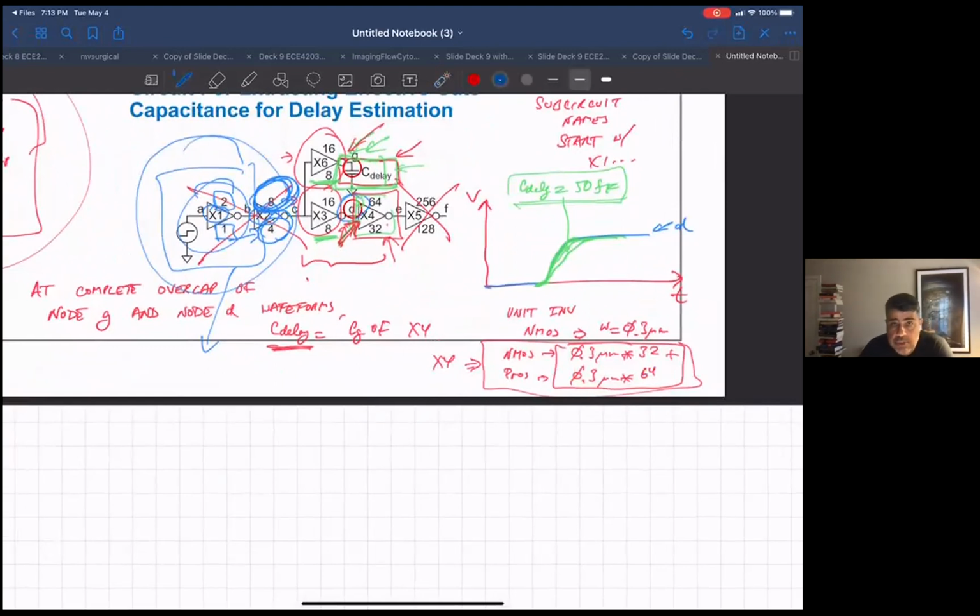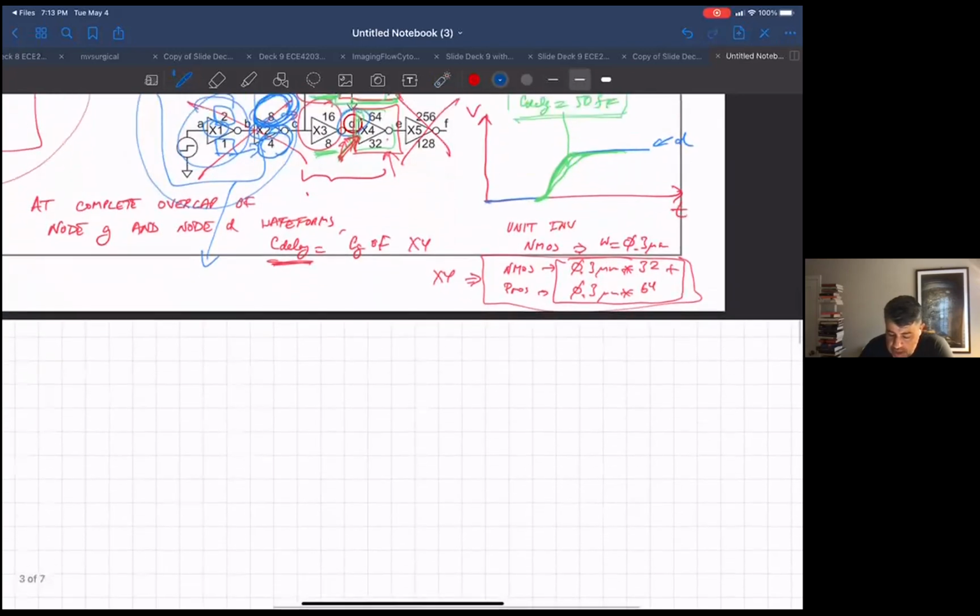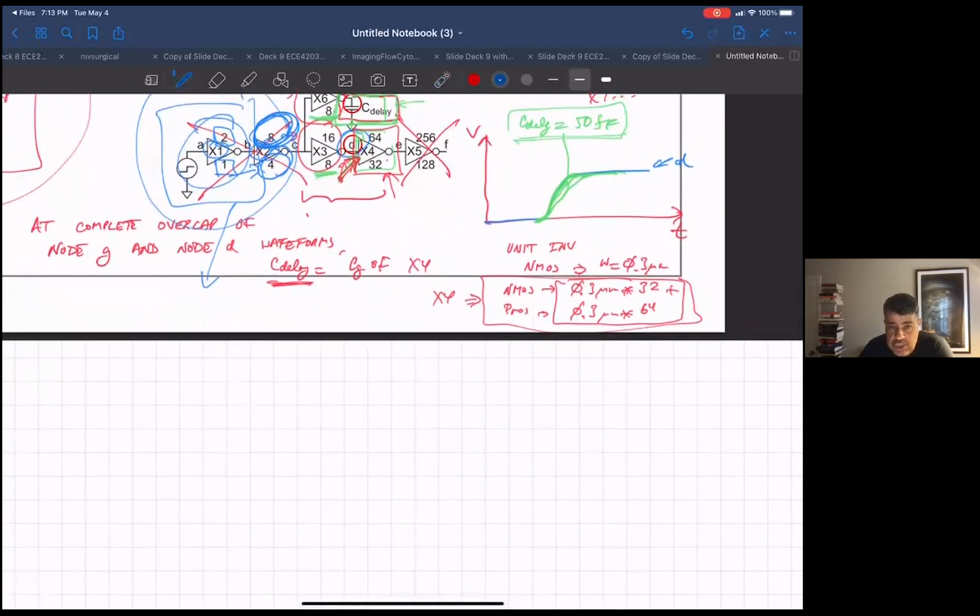By the way, guys, since you're going to be in the middle of this project, this is not the time to be shy if you don't understand anything I'm doing. Jump in and ask your questions, because you're going to be stuck if you're not following what I'm saying. So let me just run these numbers. It's 0.3 times 32, so it'll be 9.6 micron wide for the NMOS.